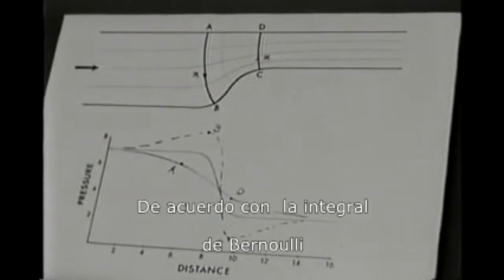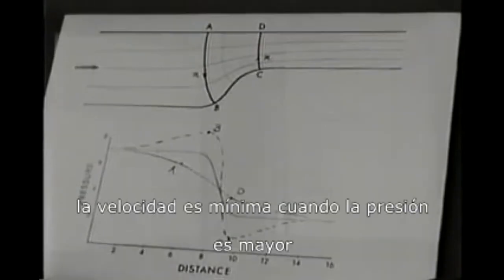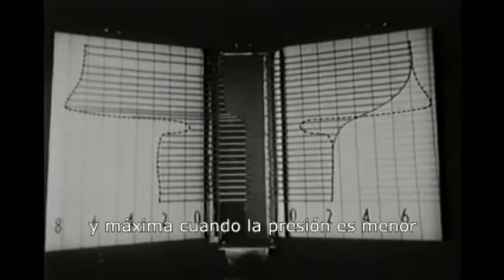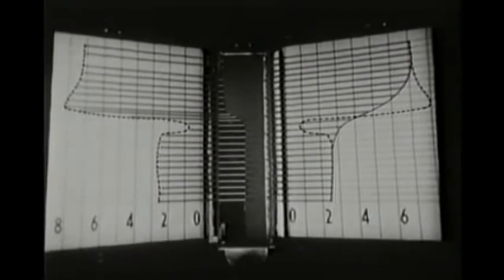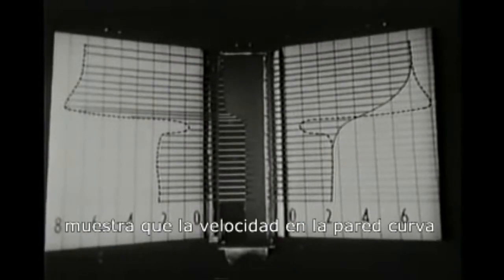According to Bernoulli's integral, which in this case has the same value for all streamlines, the velocity is a minimum where the pressure is highest, and it is a maximum where the pressure is least. The hydrogen bubbles verify this velocity distribution. The tilting of these fluid lines shows that the velocity on the curved wall is at first less than on the straight wall.